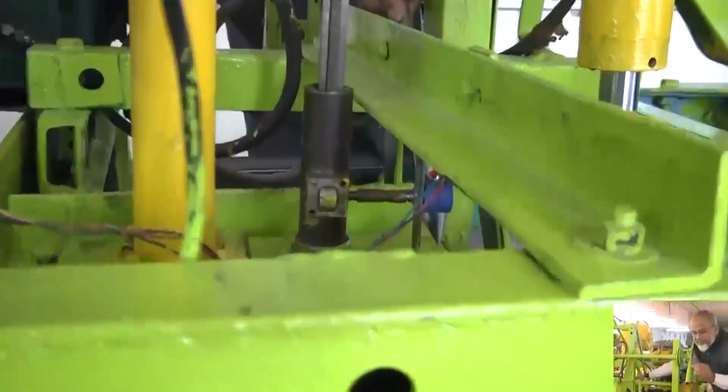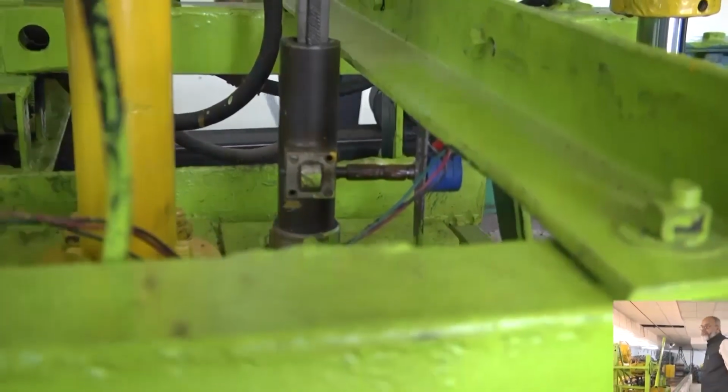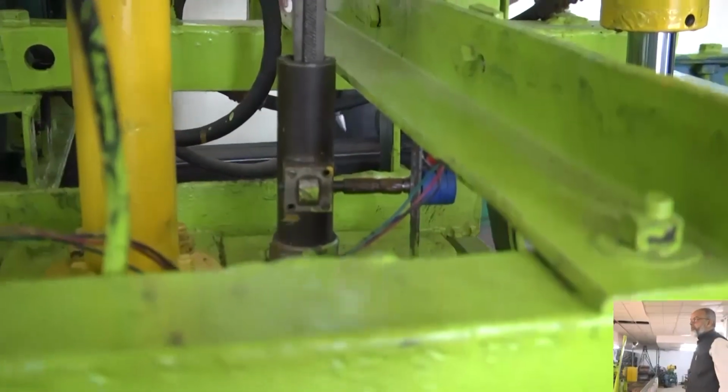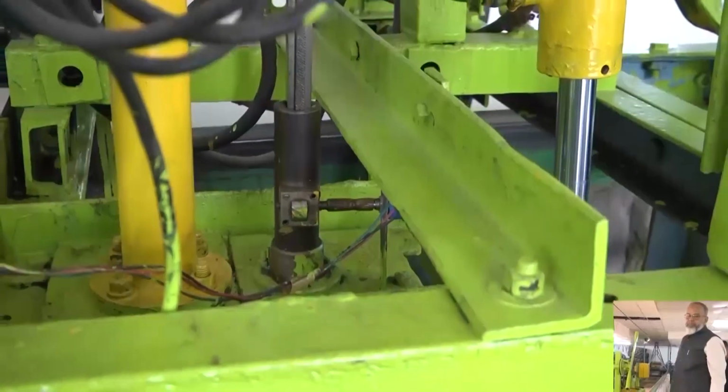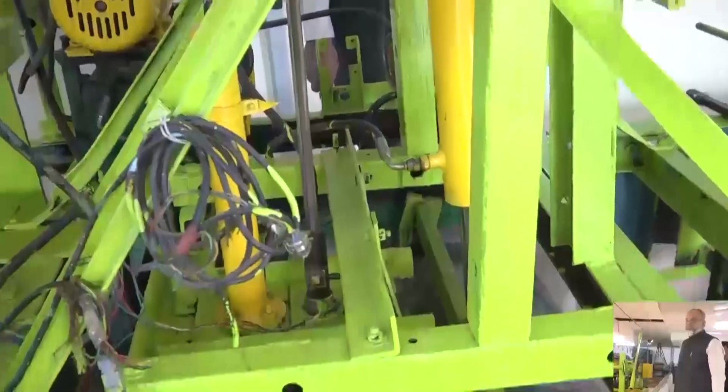Now you have to measure that cone index at different depths. So you have to measure the depth as well as the force. For measuring depth, we need to know how much depth it has entered. We have done it with the help of a potentiometer here. When you move it up and down, the resistance of the potentiometer changes. The potentiometer has already been calibrated, so once you know the change in resistance, we can find out how much depth has been entered.